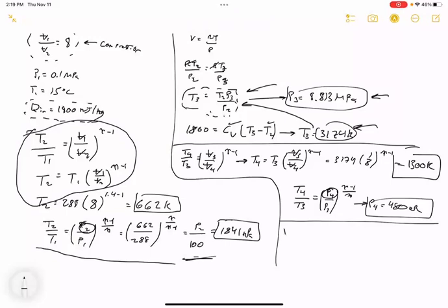So put simply, the eta, the Greek letter eta, represents efficiency. Thermal efficiency is equal to the work output over the Q input. So if the work output is like 50 and we put in 100 joules of heat in the combustion process, well, then we have a 50% efficiency.